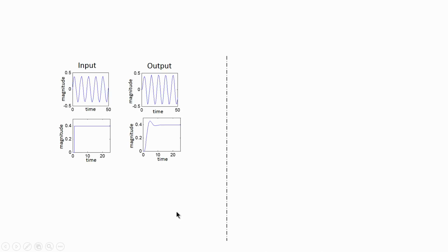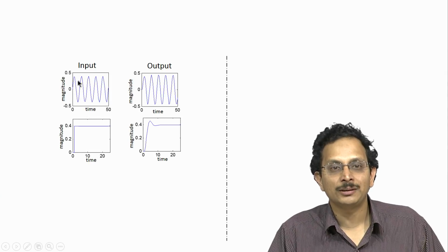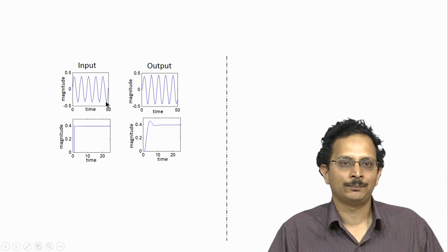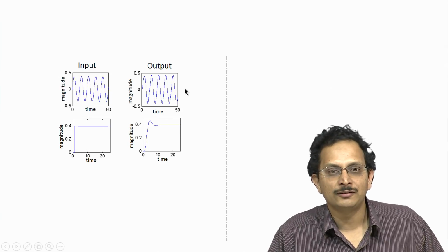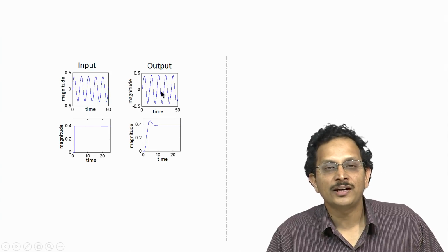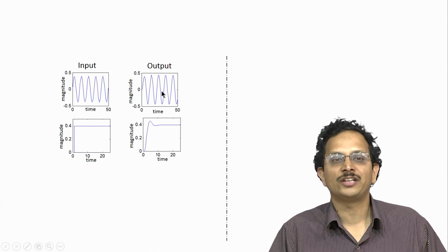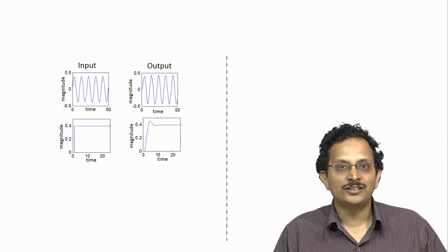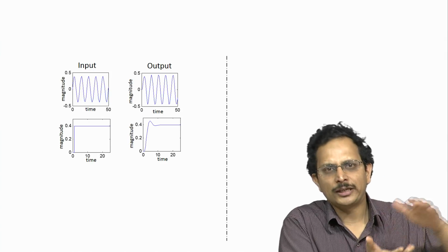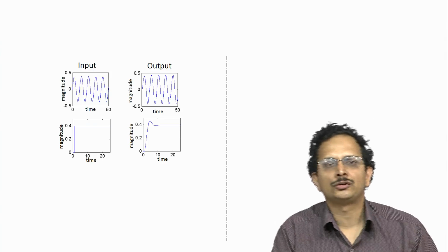Likewise, in the next slide we shall consider what would happen if we were to force our linear and nonlinear systems by using different inputs. So, on the left hand side once again I am forcing my linear system with a sinusoidal input, and what I see is that the response is also sinusoidal. It is shifted in phase of course and also modified a little bit in magnitude, but it is sinusoidal in steady state. What I can conclude qualitatively by looking at this graph is that if I provide a bounded input, namely a sinusoidal input, I get a bounded output, a sinusoidal output.